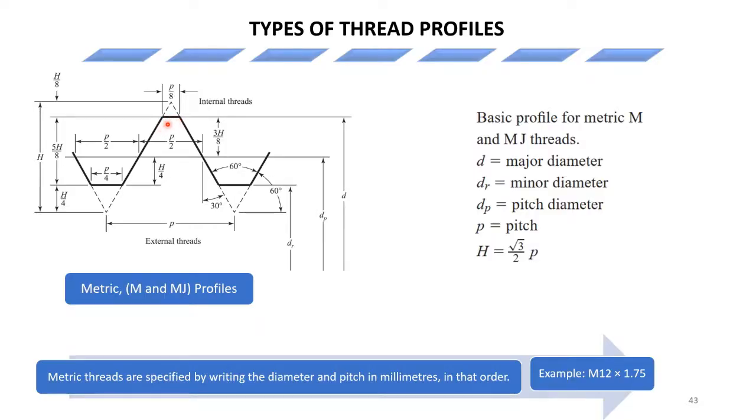All right, and that is usually used in cases where there will be a lot of fatigue, or where we want the bolt to have a high fatigue strength factor. In that case, we could introduce the fillet at the root of the thread to act as a stress relief. Okay, so that will help the threaded component to be stronger, and where there will be fatigue stresses present, that will prevent the threaded member from failing due to fatigue.